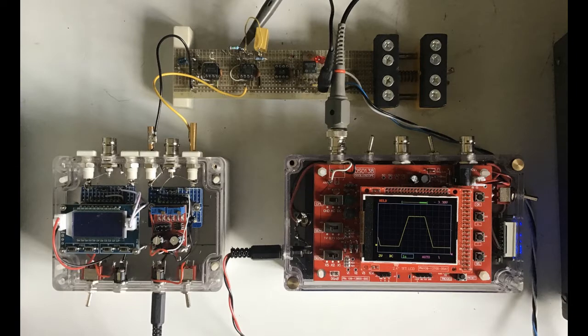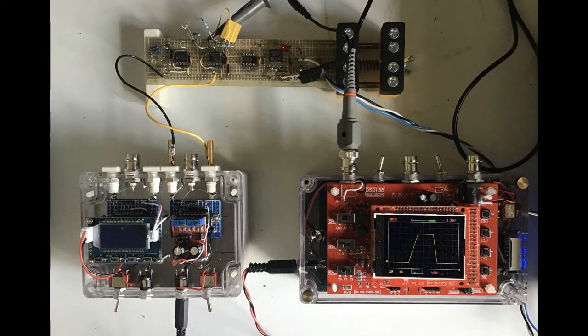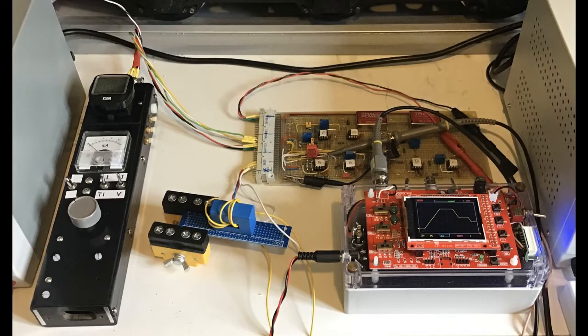These clips show test results. The oscilloscope is an eBay Chinese DSO 138, which, although it only cost £15, is very versatile. This photo shows the third circuit, now built into the control card, in action. The demand pot was initially abruptly turned from minimum to maximum. Then, after a short delay, it was stepped down with pauses. The ramp up is set slower than the ramp down.